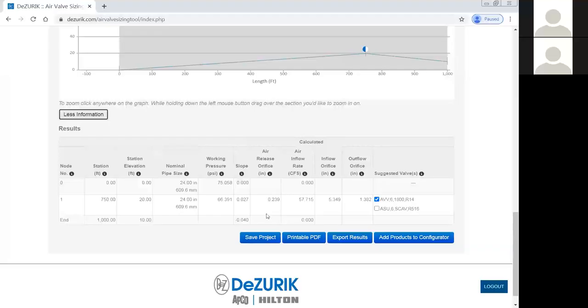Also, it shows you what size air release valve is required based on the working pressure and the flow rate. And 0.239 PSI, well, we don't have an orifice that size, but you round up to the nearest orifice and it's a 1/4 inch orifice. So anybody who wants more information, you could give them that. As a matter of fact, it always shows when we do the printout.